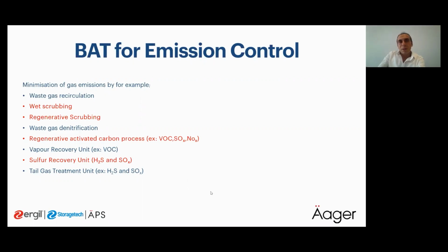The solid parts, it depends on how big these solid parts are, like PM 2.5 or PM 10. With the wet scrubber, we can capture PM 2.5 dust, but if the dusts are big like PM 10 or bigger than 10 microns, we should add some additional filters, and then the gas should come after this filter, because the sizes are bigger.